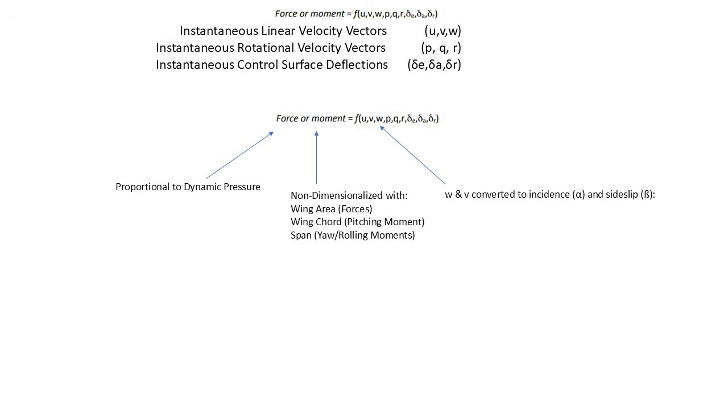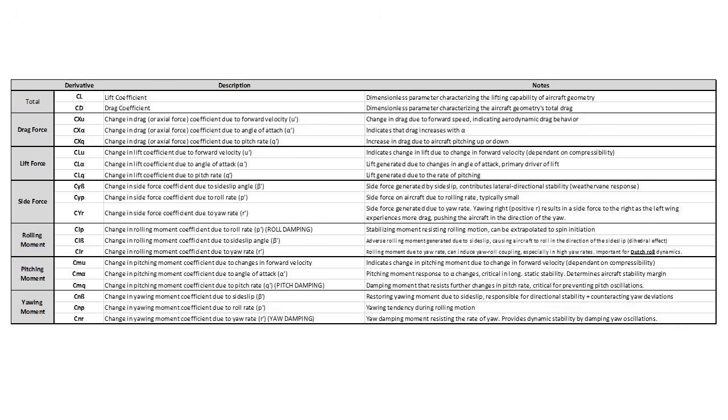We can actually gain a ton of insight into the handling and performance characteristics of an aircraft through a proper stability analysis. And to do that, we can derive what are called stability derivatives. Stability derivatives are dimensionless or aero-normalized coefficients that quantify how an aircraft's aerodynamic forces and moments change in response to small variations in flight parameters, such as angle of attack, sideslip angle, and angular velocities, for example, pitch, roll, and yaw rates. These derivatives are critical for predicting and analyzing the stability and dynamic behavior of an aircraft and enable proper control system design, ultimately ensuring safe, predictable, stable flight across various conditions.